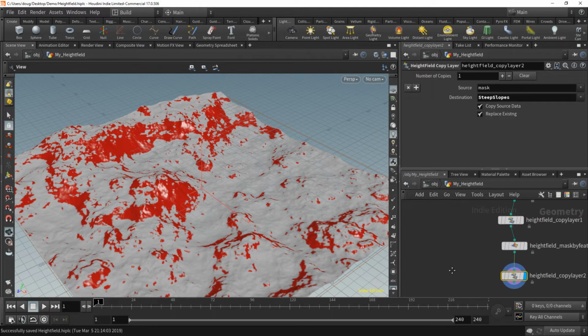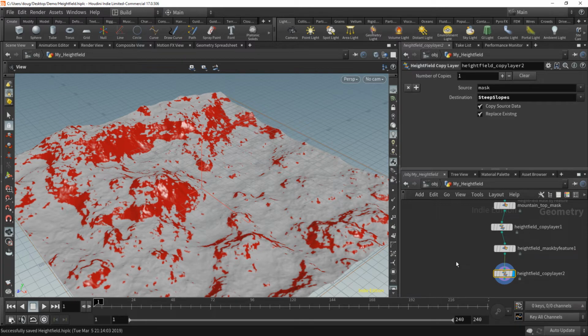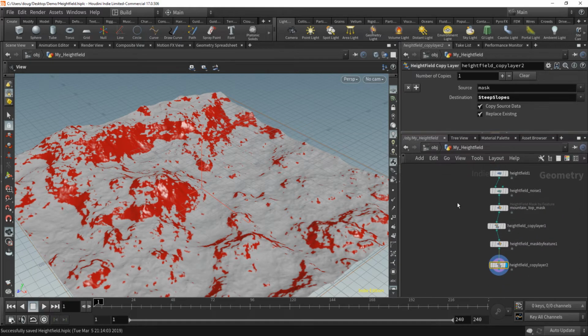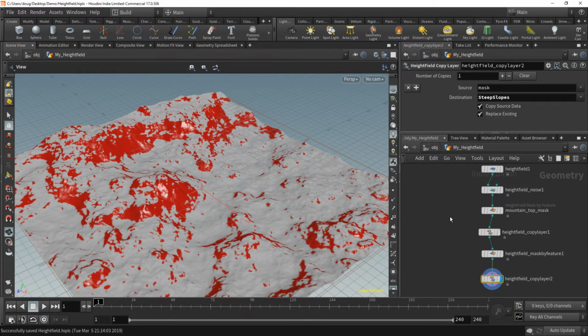And this is the trickiest one because Unreal Engine for landscapes uses weight blending, this weight painting. And so every value that it needs to paint takes a weighting of, I might be screwing this up, but it's basically a weight painting of the different layers that you have, and at least one of them needs to be non-zero. But if all of them are 1, then it's not clear to me which layer would end up getting painted. So the way I do this is I combine all the layers that I've set up, like the first 2 layers, and then invert that and use that as the layer for my base to cover everything else, basically, to make sure everything's covered. If you don't have everything covered, you'll see it show up in Unreal as a black area.